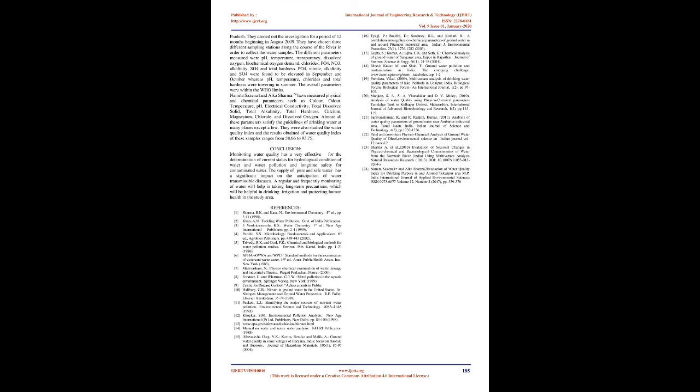Prem Lata Vikal 2009 has worked out the physico-chemical characteristics of the Pichola Lake water. He studied various parameters like air and water temperature, pH, free CO2, dissolved oxygen, biochemical oxygen demand, chemical oxygen demand, conductivity, total dissolved solids, hardness, total alkalinity, chloride, nitrate, phosphate, and sulfate. The results revealed that the values of conductivity, COD, and sulfate were found to cross the standard limits in water samples. The coefficient of correlation, R, among various physico-chemical parameters was also made.